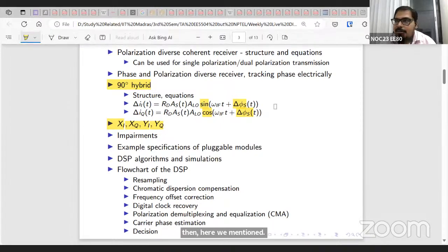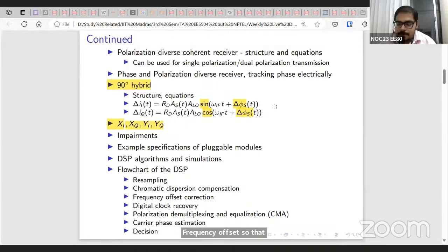So the laser that was modulated, the signal laser, is not at the exact same frequency as the local oscillator laser that you're using to detect for coherent communication. So that LO laser being slightly off from the signal laser will cause impairments, that is frequency offset.